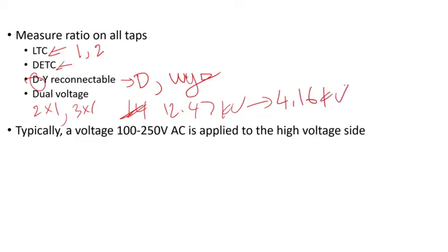So this is like in a distribution system, you have 12.47 kV, you have 4 kV, and you want to buy a spare transformer, and you want to maximize. Instead of buying 2 different spares, you say, well, what if I buy 1 spare transformer and I'm going to store it? That way, if I have a transformer that fails on the 12 kV side, I can use this spare. If I have a transformer that fails on the 4 kV side, then I can use this spare.